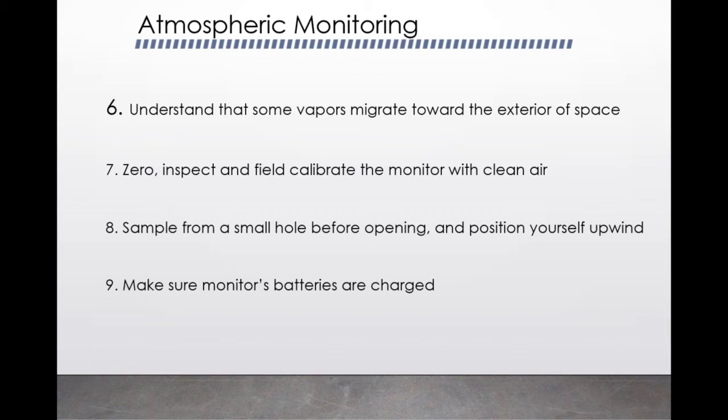Sample from the small hole before opening, and position yourself upwind, so just in case that there is any kind of air coming out of that space that is toxic to you. If you're upwind, meaning the wind is to your back and it's blowing away from your face, then now you can know that once you open that space and the gases come out, it's blowing away from you rather than blowing to you.